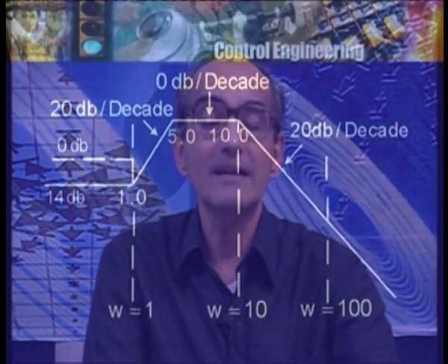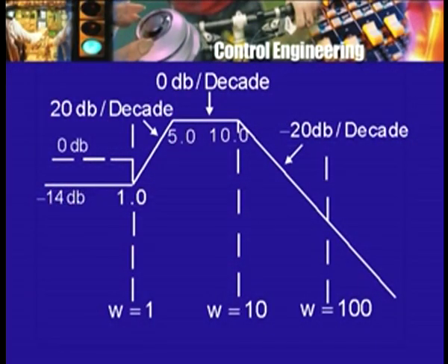So what is the net effect? The 0 contributes an increase in gain, the 2 poles are yet to make any significant difference. Therefore the net result is an increase in gain. An increase in gain at what rate, so to speak? 20 dB per decade. And so if this was the curve so far up to the corner frequency of 1, then from here it will start growing at the rate of 20 dB per decade. So one shows it, or one thinks of it like this.